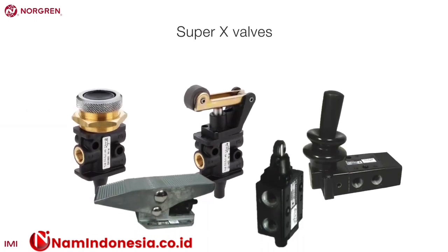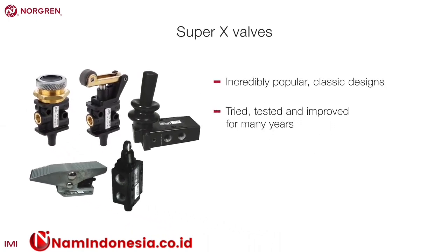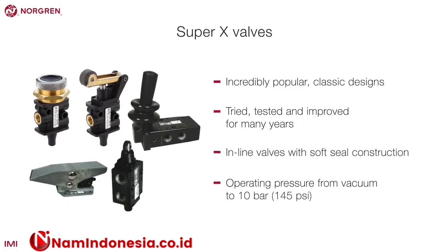Super X manual and mechanical valves are incredibly popular classic designs that have been tried, tested, and improved for many years, making them extremely reliable. All are inline valves with soft seal construction and have an operating pressure from vacuum to 10 bar or 145 psi.